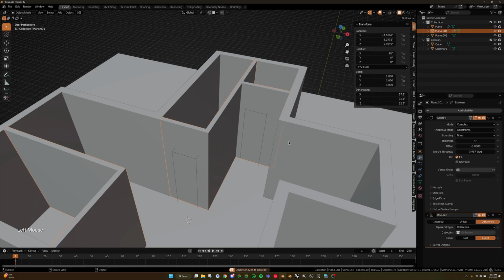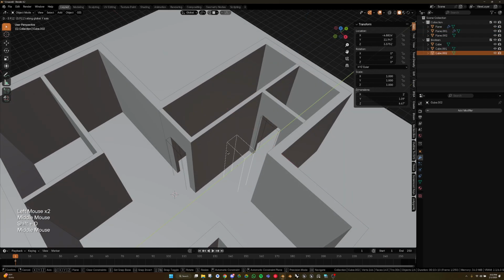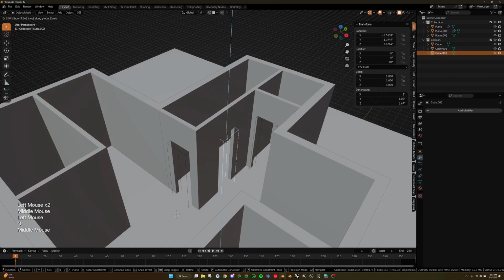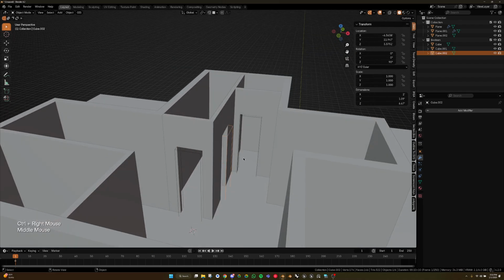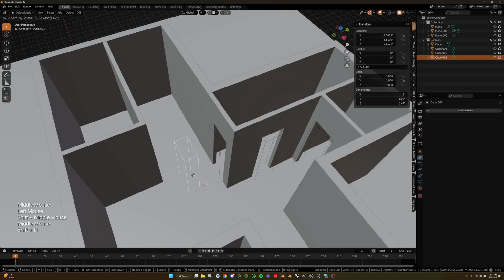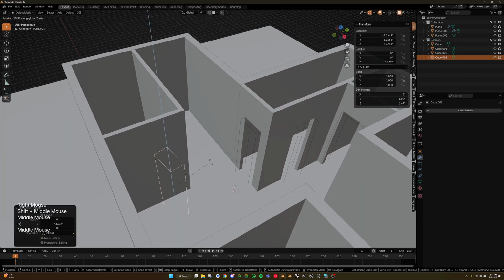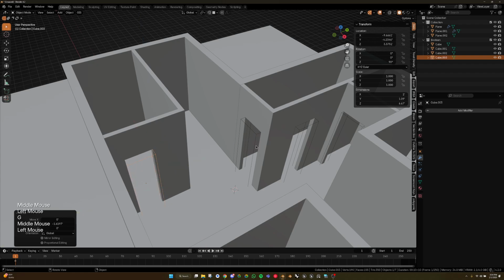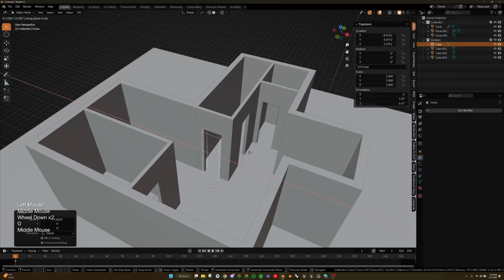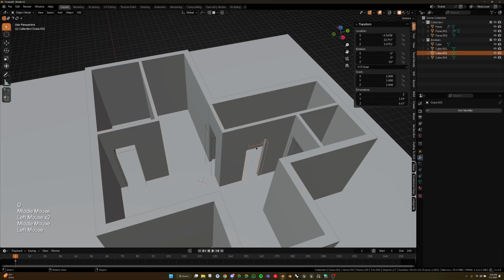And then once you click on your walls, you can click on Boolean. And now, wherever you put these Booleans, honestly, keep it on fast. The Booleans are a little tricky in Blender, but it does the job for the most part. And then you can rotate this 90 degrees, and then let's say you want a door here. And you could just easily, you know, in architecture, you're always changing the design. So it's low effort to just kind of move these around.